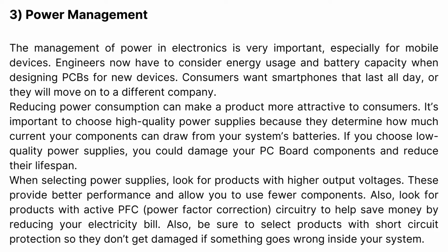When selecting power supplies, look for products with higher output voltages. These provide better performance and allow you to use fewer components. Also, look for products with active PFC, power factor correction, circuitry to help save money by reducing your electricity bill. Also, be sure to select products with short circuit protection so they don't get damaged if something goes wrong inside your system.